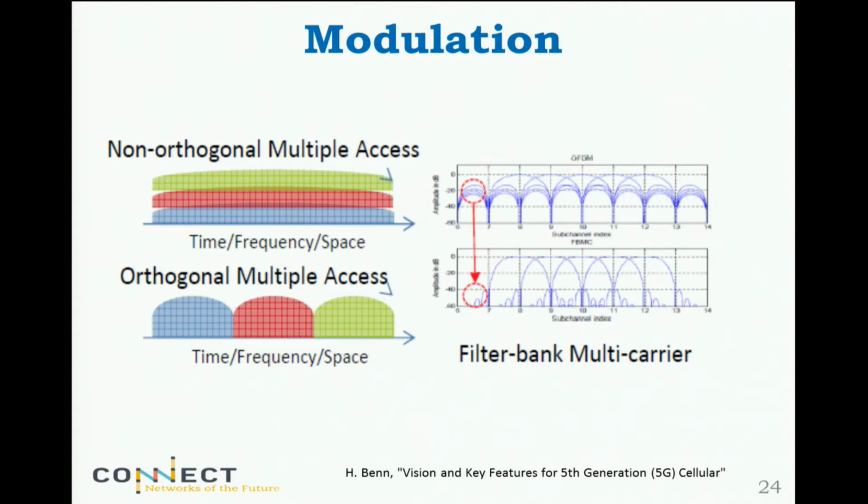Right. I actually read the paper where they were claiming that single carrier could probably be the option. Yeah. So again, it's not for sure that you always need high data rate. Multi-carrier is good for high data rate. But if you have applications that focus more on low latency and don't care too much about throughput, single carrier might be the option. In fact, many of these machine type communications focus a lot on responsiveness, right? Few bits to be transmitted, but it has to be quick. And the de facto standard at the moment is GSM, right? 2G.